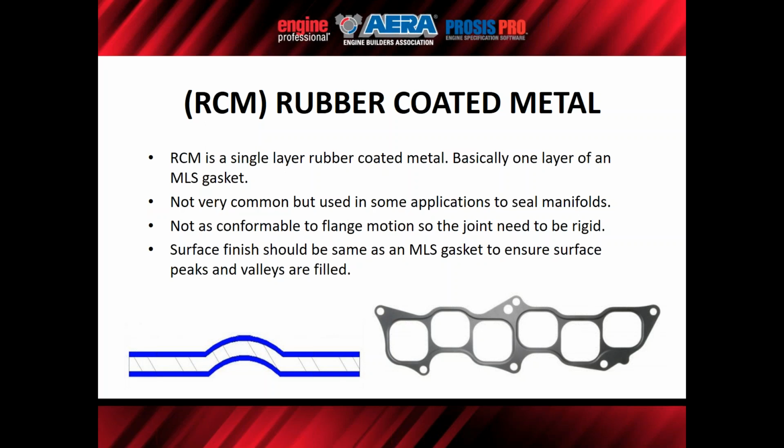You could also replace this particular design gasket with a fiber-based product and be successful. If you want to reduce cost for the end user, you can take that particular OE design and just make it into a fiber-based material, maybe with a core for the rigidity there, and cut down the cost. The gasket may not last as long as the OE, but you don't need it to normally. By the time this reaches, say, 100,000 miles, you only need the car to go another 50 or 60,000. You could use a fiber-based product for it instead and move on. Or you could just replace it with the OE style as well.